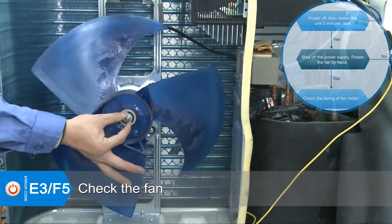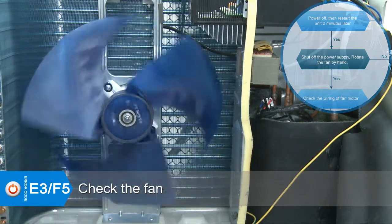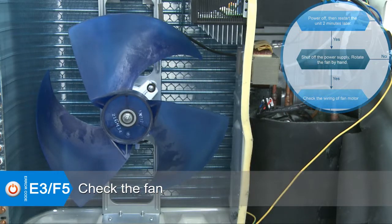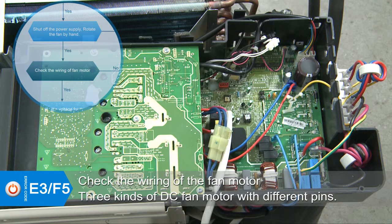Rotate the fan by hand. Check whether the fan is blocked or rotating normally, and whether the screws which fix the fan have been tightened enough. If the fan is normal, check the wiring of the fan motor according to the wiring diagram.